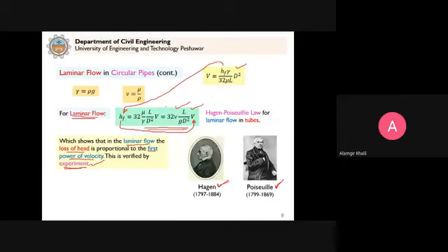And in this equation here, you can see there is no friction factor. You see what is involved: the velocity, L that we can easily determine, acceleration due to gravity, diameter, kinematic viscosity. There is no friction factor here, as we see in the Darcy-Weisbach equation. So it means the head loss that we calculate in case of laminar flow is due to the viscous forces that are involved. Clear? So the pipe roughness has no effect in case of laminar flow. If you have any question, note it down and you can ask in the break time.